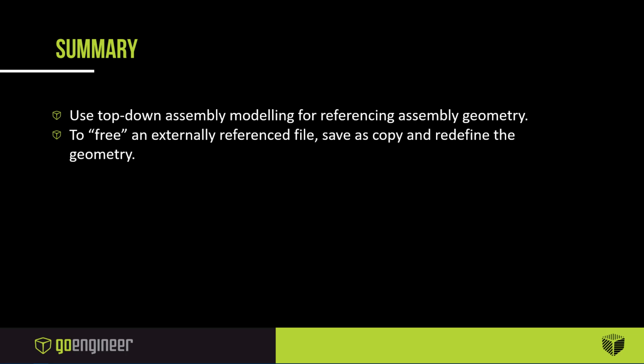Do virtual parts enlarge the actual mass of the overall assembly, or are there weights only in the assembly? So yes, the masses are included in the calculations of the assembly. So you can just test that out if you want: create a virtual part, look at the mass of it, and then delete it, then you can see the differences in the two masses. So it does contribute to the mass of the overall assembly.